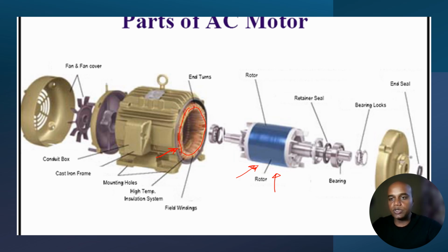So it is very interesting to understand how the rotor of the induction motor runs. And for better heat dissipation, we also deploy a fan over here, which further increases the efficiency of the induction motor. As I stated earlier, based on the rotor design shown over here, we have two types of rotor design for the induction motor, and therefore two classifications of the induction motor. One is the squirrel cage and the other is the slip ring induction motor.